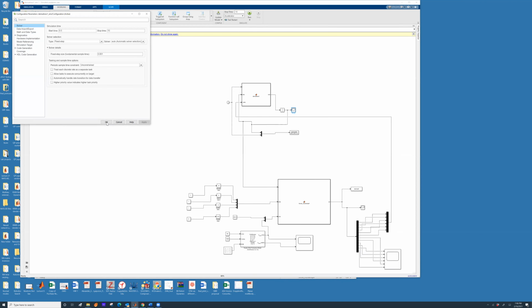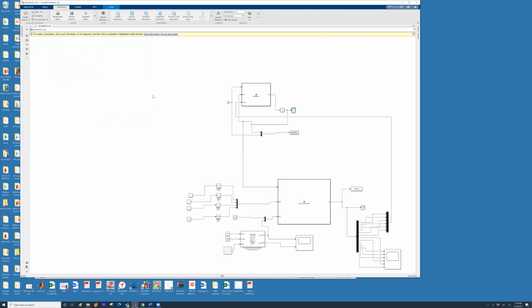I don't know what your configuration is, but I promise you there were 2 students who had their simulation crashing, but then they freed the RAM and changed certain parameters. They changed the solver and the step size, and then the simulation stopped crashing. Your simulation should not crash if you are using MATLAB 2020.